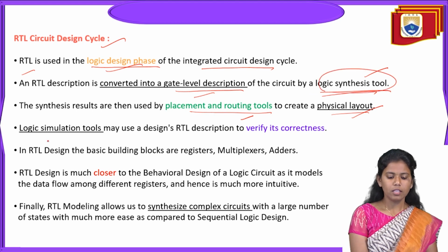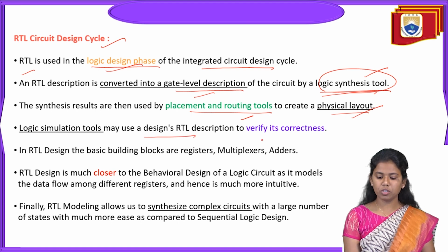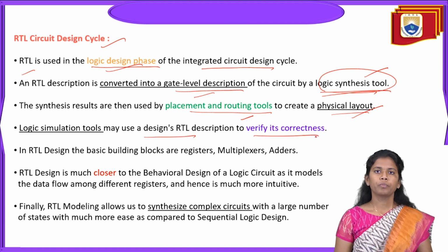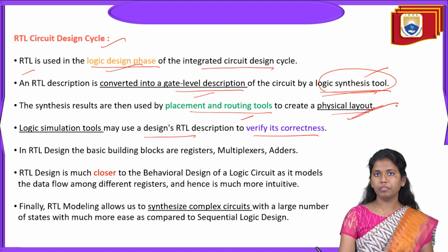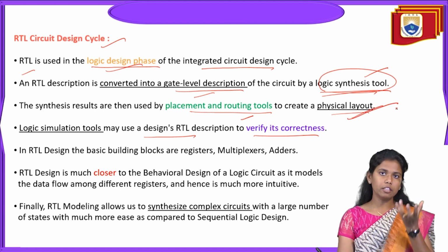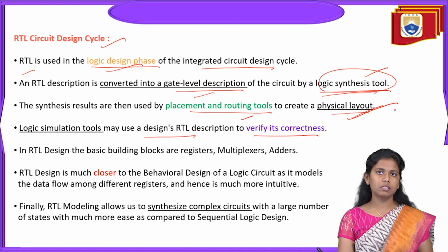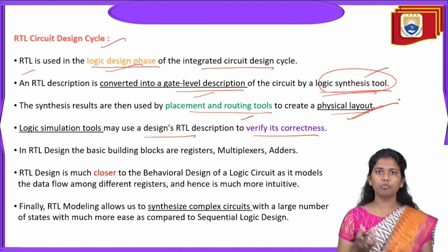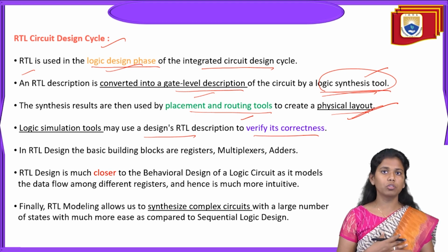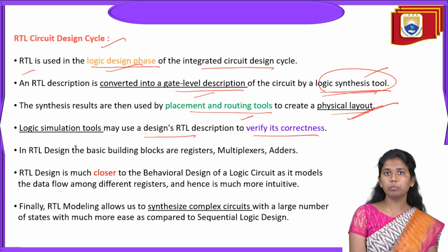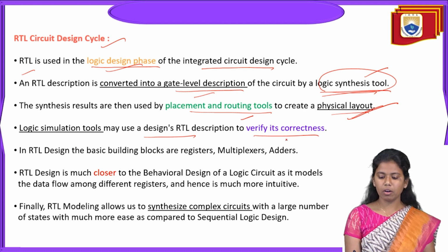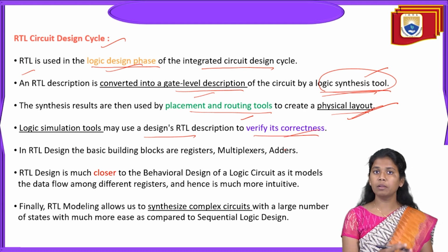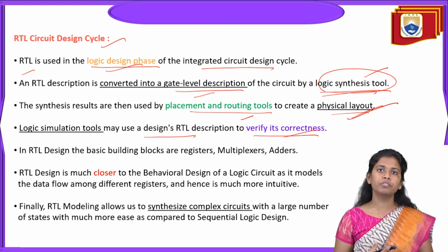And then logic simulation tools may be used with a design's RTL description to verify its correctness. So after getting the physical layout, we want to examine whether the layout, consisting of all the elements, all the metals and the color coding, is fine or not. Logic simulation tools will help us verify the correctness of this particular physical layout.